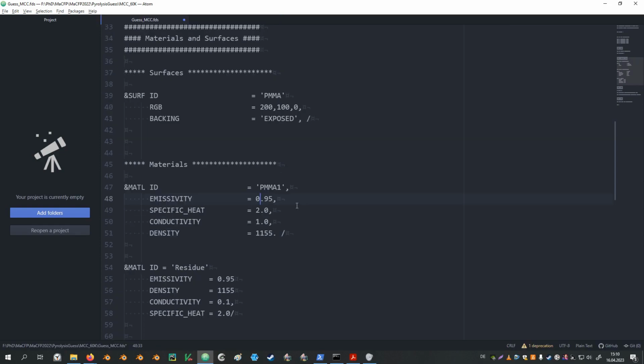Future Tristan here. If you're interested in the mass loss or the energy release, meaning the TGA or MCC, you can use the video as presented. However, if you're interested in the energy consumption, meaning the DSC, then you need to also specify the specific heat and also the heat of reaction, which is not covered in this video.